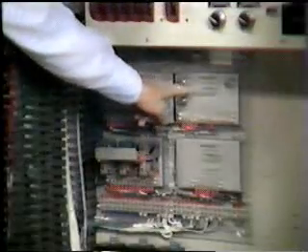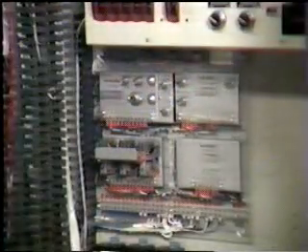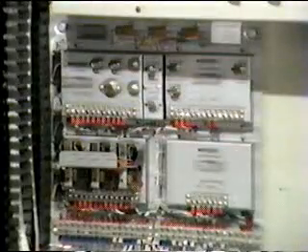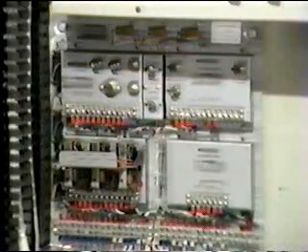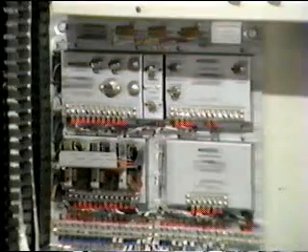Next to the amplifier is the ramp generator. The ramp generator controls engine acceleration between 90 and 100% speed and provides for reduced engine speed during compressor cleaning. The governor receives signals from a magnetic pickup and from current and potential transformers. The governor sends signals to the servo actuator to make adjustments in engine speed.